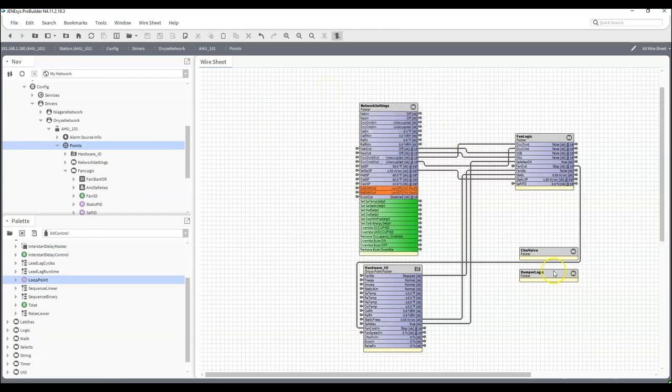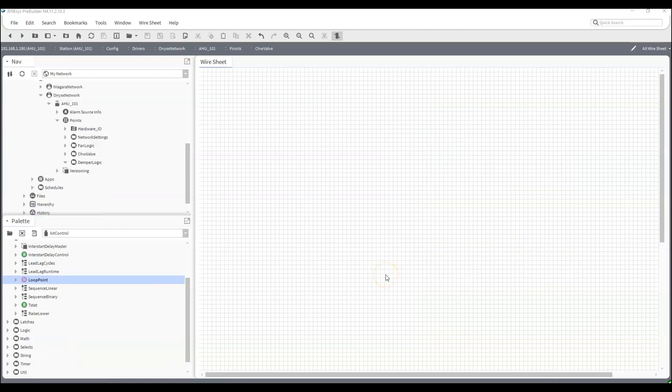And now we're going to get into the chill water valve logic. So for our chill water logic, it's going to be quite simple. We are just going to modulate the chill water valve to maintain a supply air set point without the use of economizer.